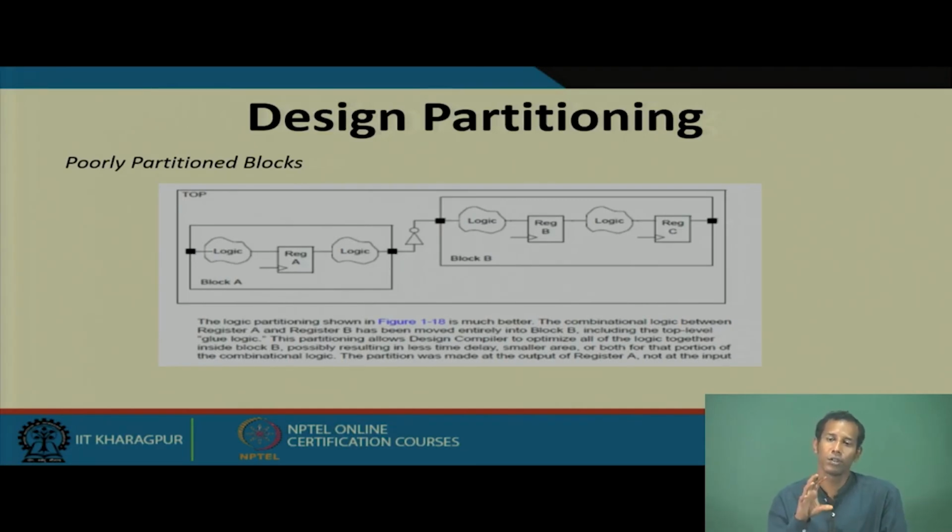So, that is why whenever we place the design, we have to remember, or the tools have to remember, or we have to tell the tool, so that it can place the design closer where there is interconnected connectivity, or interdependent connection, between the two blocks, two sub blocks or two blocks. So, if you see this is block A and this is block B, which are part of the main module, which is the top.